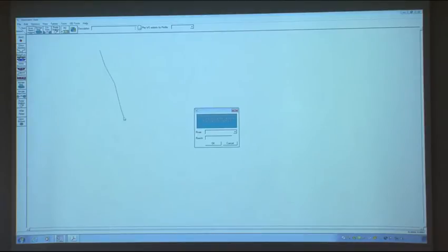If you double click, you'll see a small window, okay? Select an existing river or enter a new river. The river name is 16 characters maximum, and the reach name is 16 characters maximum.